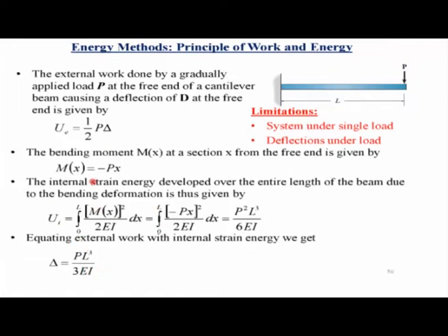This is one of the simplest ways of calculating the deflection of beams using the energy method, but there are some limitations. If you do it this way, you can calculate the deflection only under a single load at one time, and it will give you the deflection at the load itself. It will not give you the deflection at any other point of the beam. So far we have not introduced any virtual load into the system. It was an applied load that we used, and using the method of conservation of energy, we have seen how we can calculate the deflection under the load.